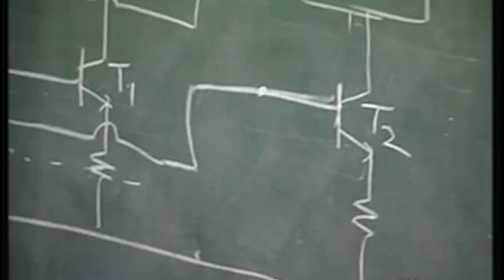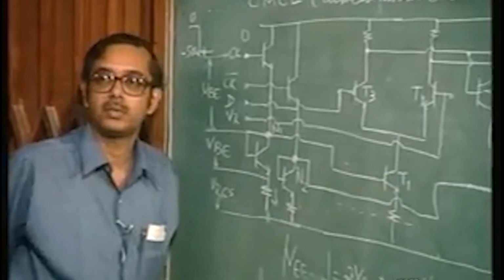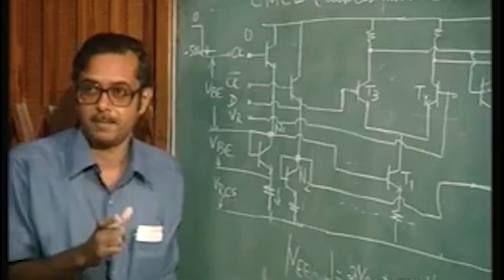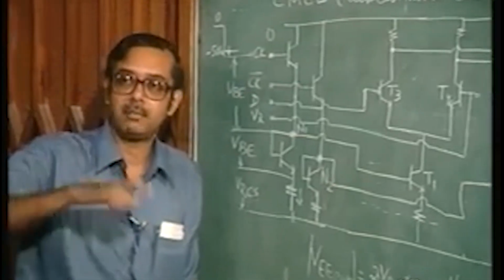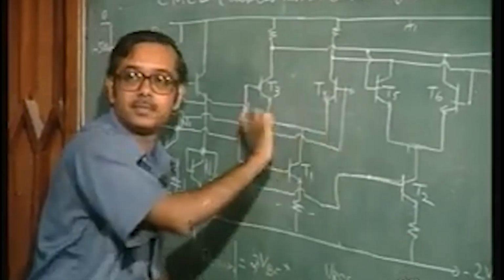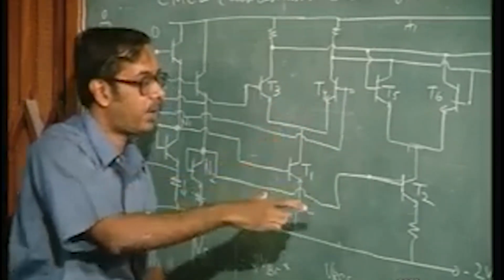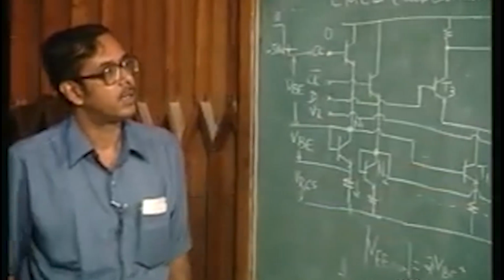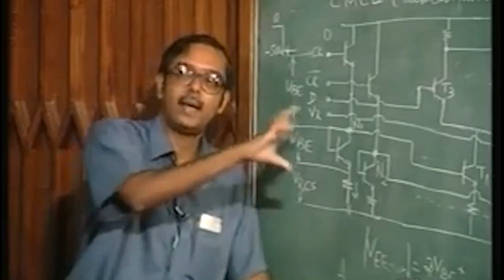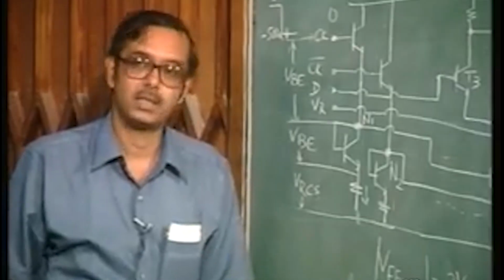That is basically depending on which node, N1 or N2, is high, one of the branches is going to control the current. So, here with a current mirror, instead of an emitter coupled structure, we choose which branch is going to be conducting. And in the process, the power dissipation is reduced because we require a lower power supply voltage. At the same time, the current requirement is also less.